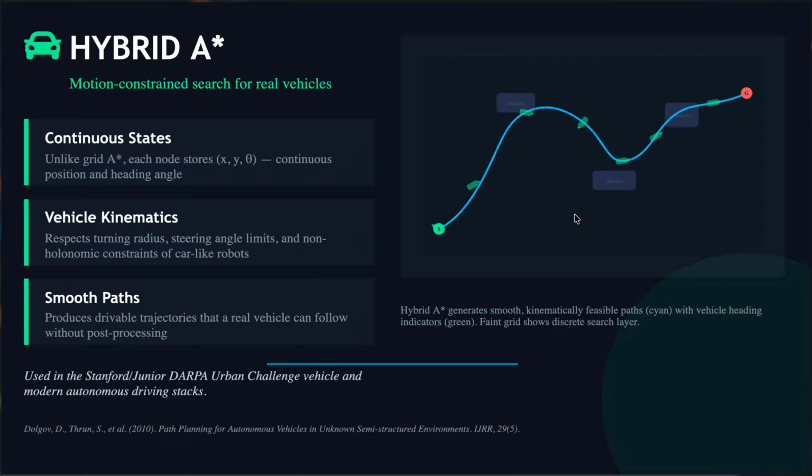Tesla uses a combination of D-star and A-star to ensure that you get the best out of autonomous driving. So for instance here, the algorithm also checks that it respects the vehicle's kinematics, which basically means it also ensures that there is time and space given, and also the turning radius, according to the vehicle's configuration.